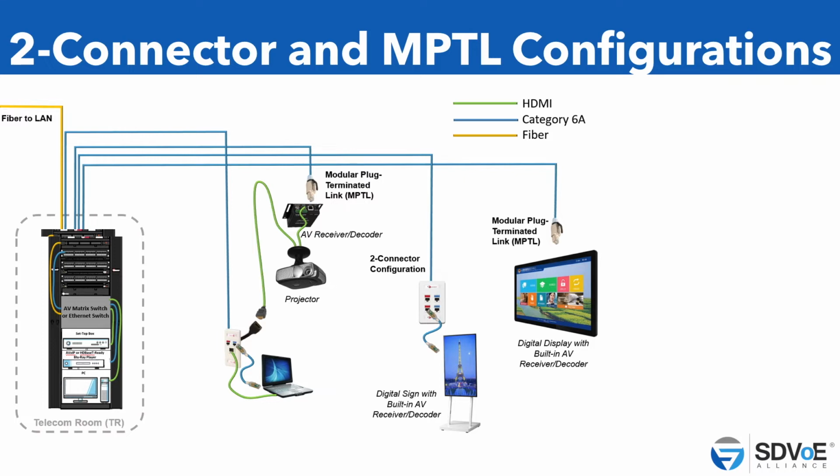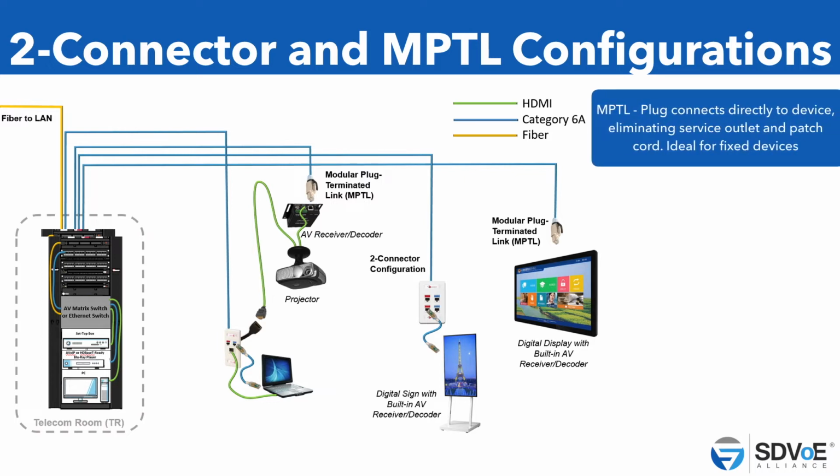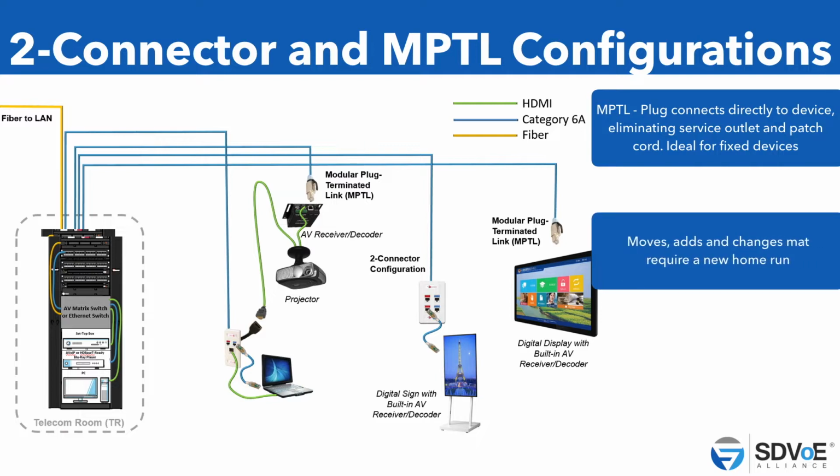So what we've done at Siemon is develop a new, fast style of connector, similar to an RJ45, that would take a fully shielded cable from Category 6A, Category 7, Category 7A, and be able to terminate it in around about a minute, so we can then have a direct attachment directly into the equipment that we're working with. Now this is going to make our life a lot easier, because it means faster termination than the way in which we work.